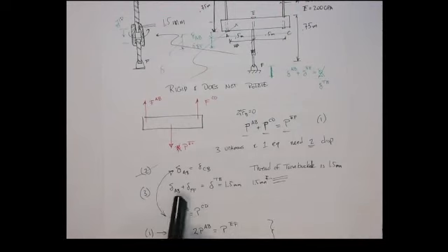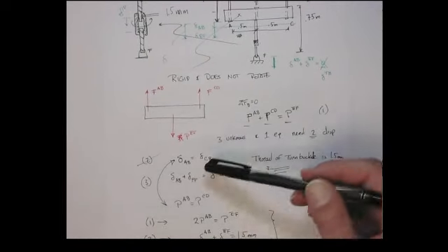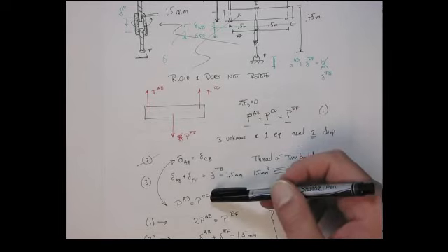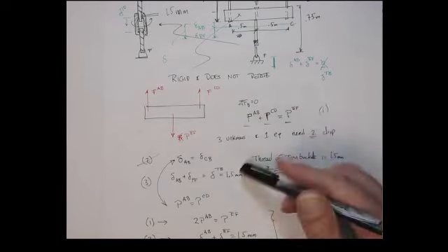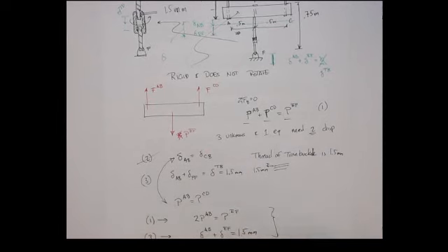But since you're solving for these coupled systems, you need to have the same sense on P as you do on the deltas. So in other words, if you just always assume that delta being positive means elongation, and that the internal reaction force is positive in tension, then you'll always be consistent. And I think that makes sense. If you start flipping them around, then you certainly can do it, but you just have to be very careful about the signs.